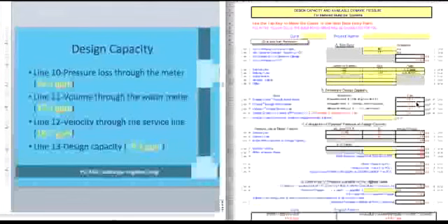But let's keep going. So the allowable flow of the water meter is considered to be less than or equal to 75% of the maximum meter capacity. And given the fact that we've got a 1-inch meter, the worksheet has gone ahead and calculated that as 37.5 GPM. Okay.